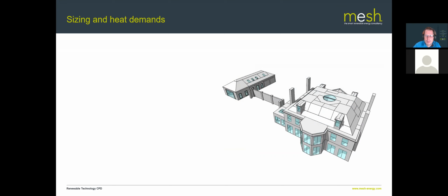So here's our typical house, and we've made all the insulation upgrades we can. We've thought about where all the plant's going to go, and we've started doing some design for it. We've decided where it's going to go on the plot. If it's new build, obviously; in retrofit, we can't viably move a house around to make it orientate more successfully. But here's a quick rundown of how we would do the design. We'd start by determining the design temperature, which is simply a lookup based on where the house is located and the elevation of the house above sea level.